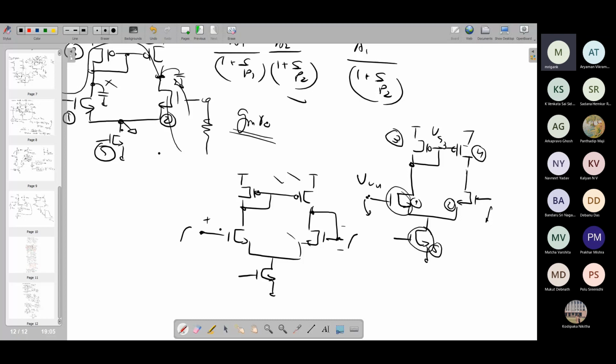So you see, if I assume that the gain at this node is very small, right? From here to here is the diode connected load, so the actual gain is coming here. If you simulate this circuit and apply a differential signal, the gain at this node will be much smaller than at the output node. Now assume that this signal is in a fully differential amplifier. What happens? Both signals are exactly similar and opposite, right? So peak to peak magnitude, you have a resistive load differential amplifier. Here you will get exactly the same peak to peak amplitude in opposite directions, differential. But this is an asymmetric load.